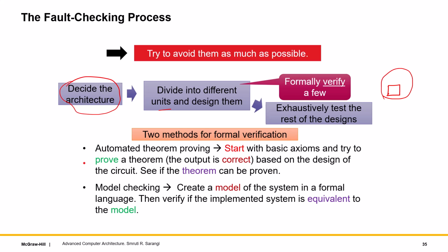So there is a gold standard of correctness called formal verification, which is a formal approach where you basically say that one circuit, which is the one that you built, is equivalent to an ideal circuit. An ideal circuit may be an ideal adder or an ideal multiplier, right? So both of them are equivalent. An ideal circuit, of course, is hypothetical, it's a mathematical object. And the circuit that you built is something that you built using a hardware language like Verilog or VHDL.